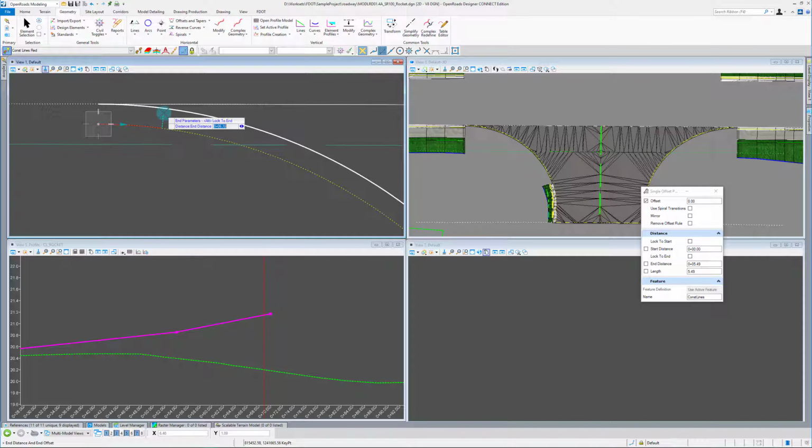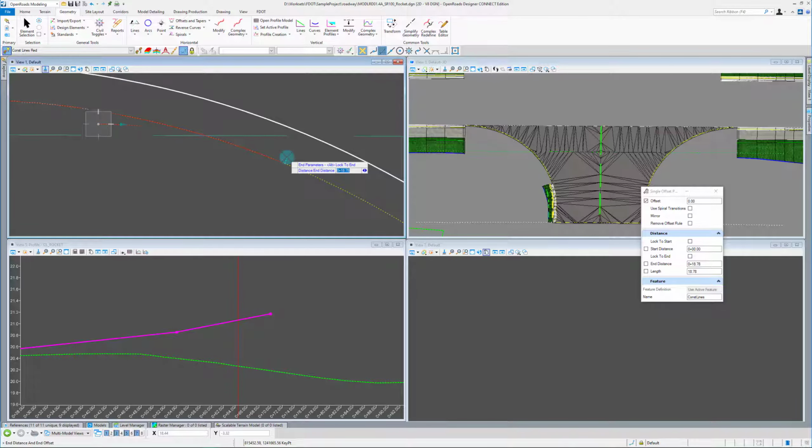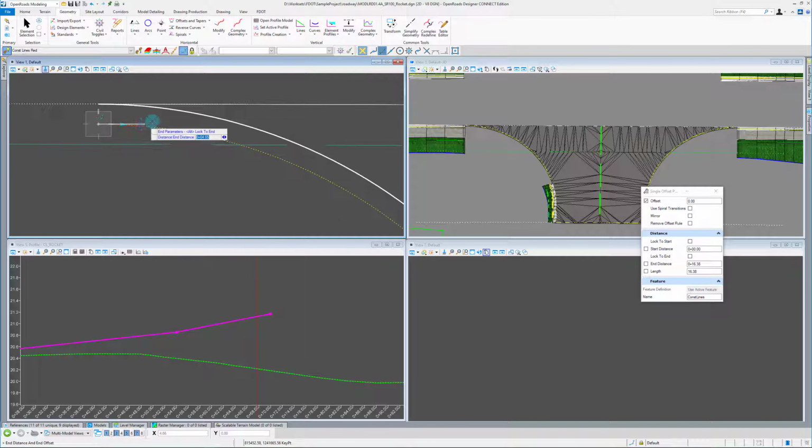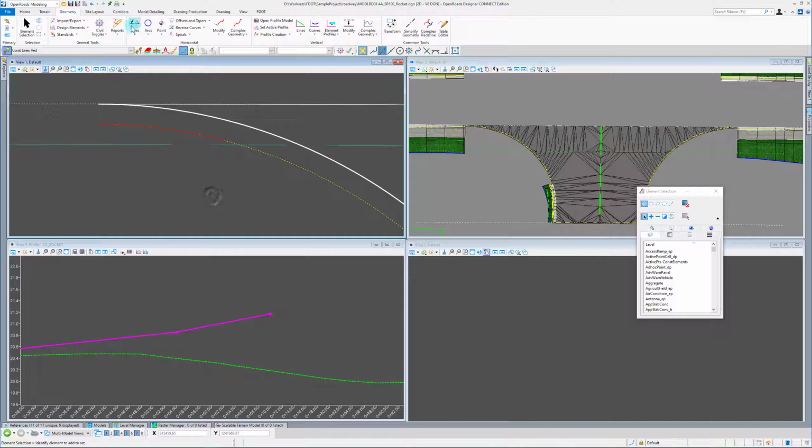And then we know we need 7 feet for the flare, and I do a 5-foot ramp. Some of these curb ramps require a 4-foot minimum at the back of curb or the face of the sidewalk curb. So doing a 5-foot ramp along the back of curb ensures that I'll have that 4-foot minimum at the back of sidewalk. So that kind of comes out to 3 feet plus 7 feet plus 2.5 feet, which is 12.5 feet. So I'm going to draw that in there.